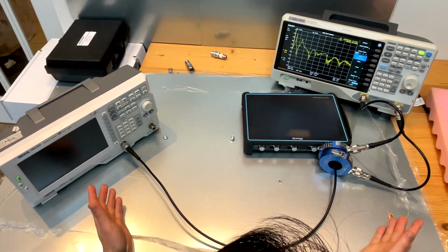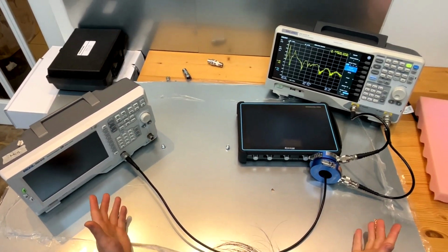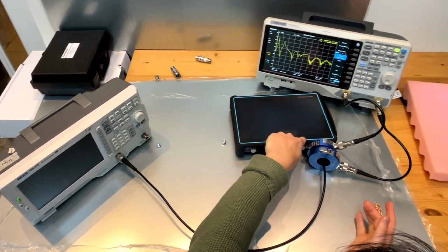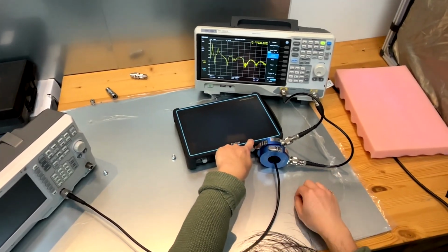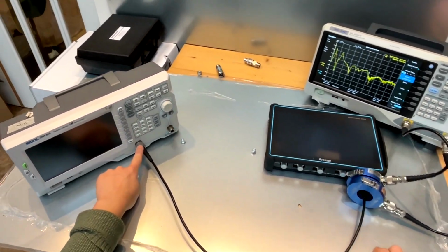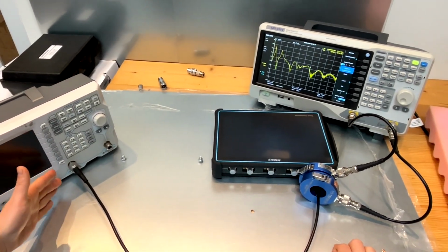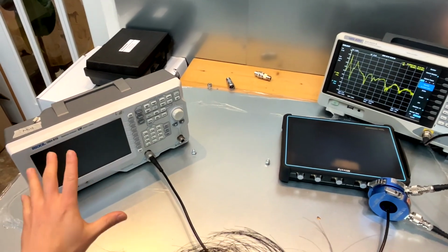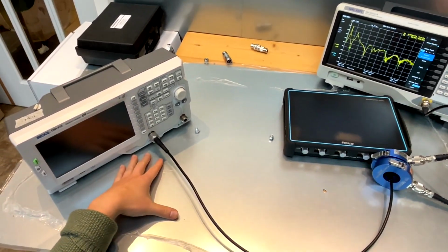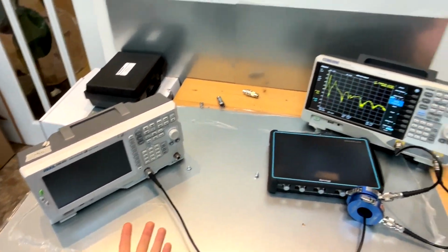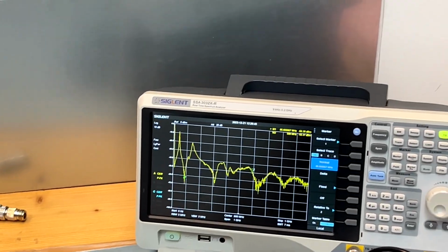Perhaps this gives you a better idea. As you can see in this case, this represents a relatively lower impedance to the common reference. This end of the coaxial cable again perhaps represents a lower impedance to the common ground, and as you can see, we again shifted the resonance frequency.